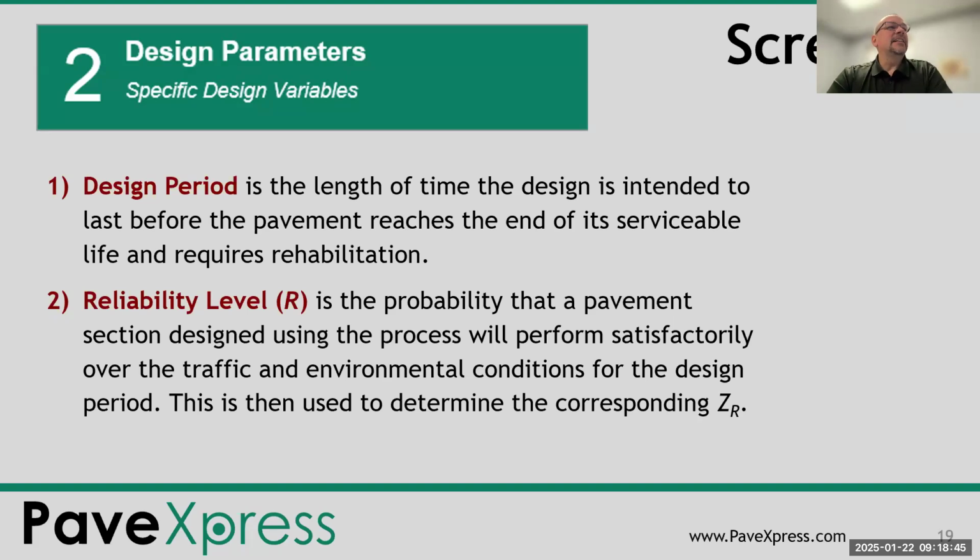Basically going through the design parameters, design period is the length of time the design is intended to last before the pavement reaches the end of its serviceability life and requires rehabilitation. So defining that design period has a lot of effect on your traffic, because then you're going to extrapolate that traffic over that design period to come up with your traffic loadings or your ESALs.